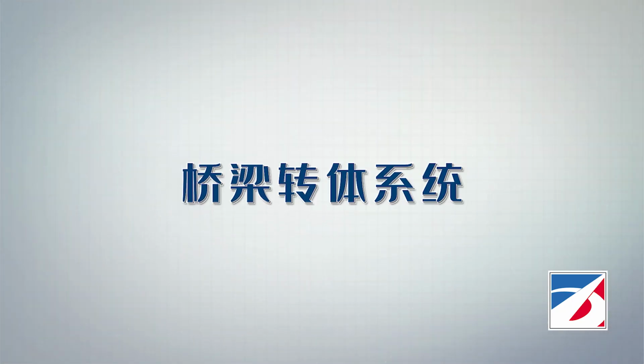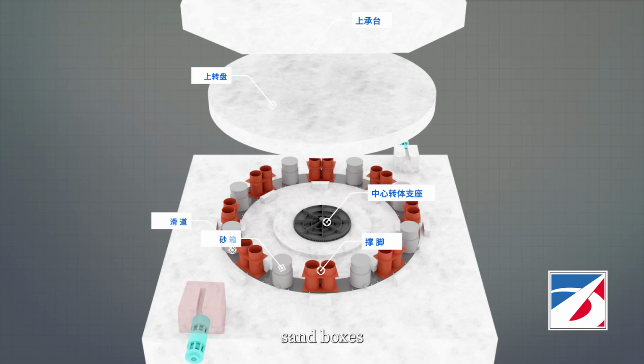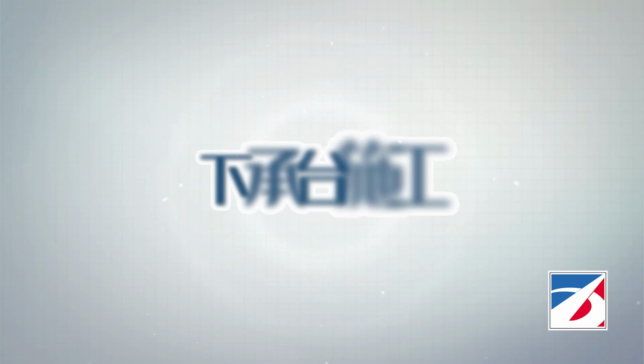Bridge swivel system. The bridge swivel system primarily consists of the upper bearing platform, upper turntable, central swivel bearing, sliding tracks, support feet, sandboxes, jack reaction seat, boosting reaction seat, and swivel traction system. Installation and construction process of swivel device.